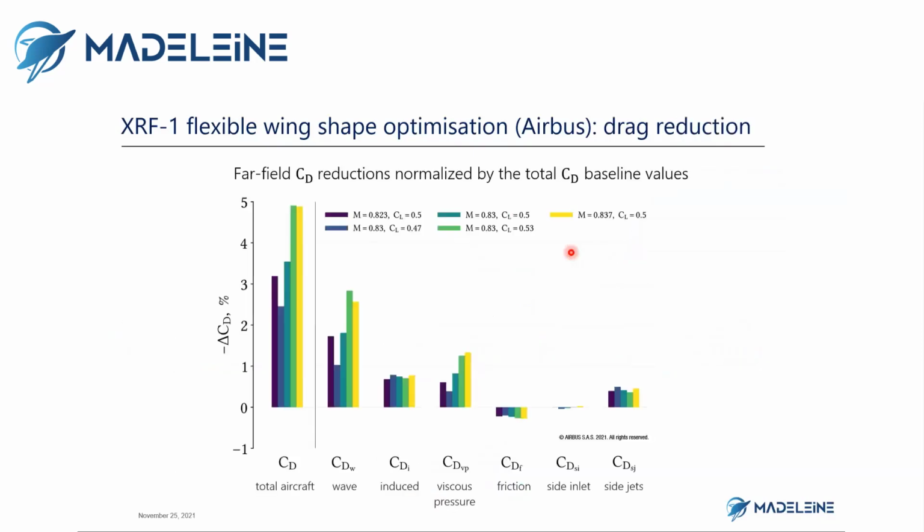Besides this convergence, we are also interested in having a more detailed look into the physical origins of the drag reductions. For this purpose, we perform far-field drag breakdown analysis on the optimal solutions. These analyses allow us to decompose drag into different physical components, such as wave drag, induced drag, viscous pressure drag, and so on.